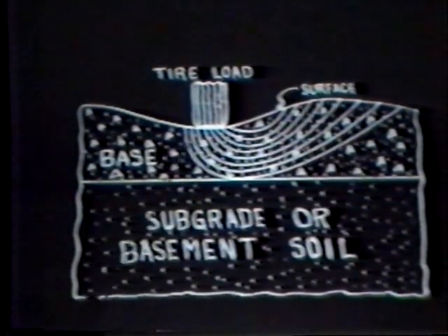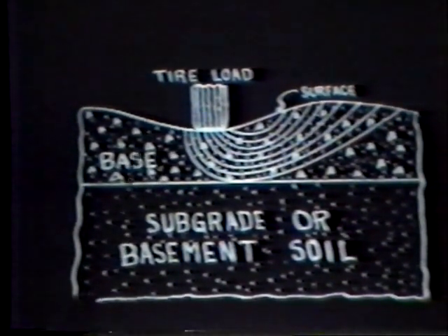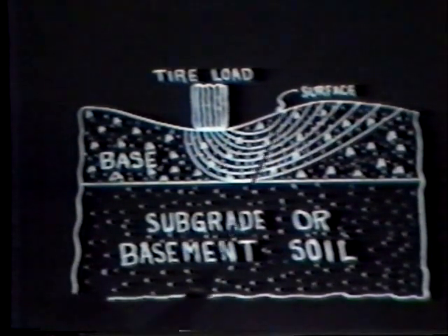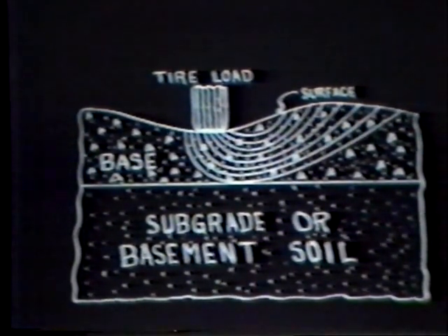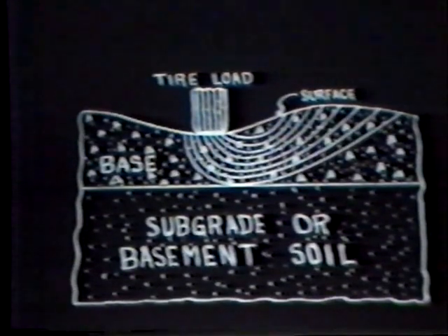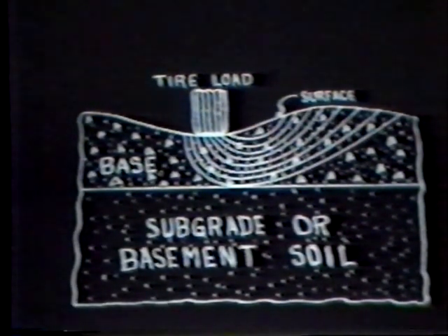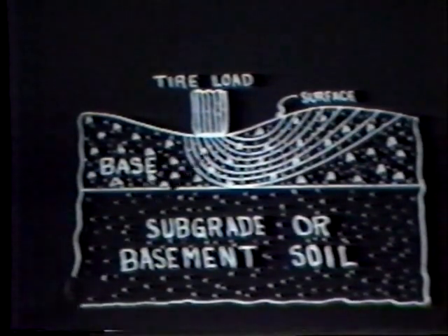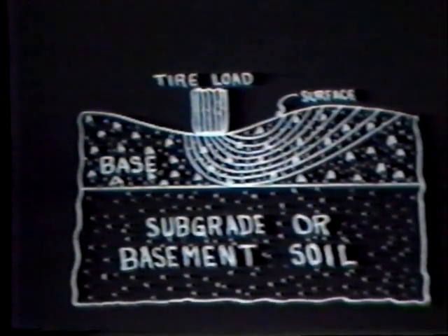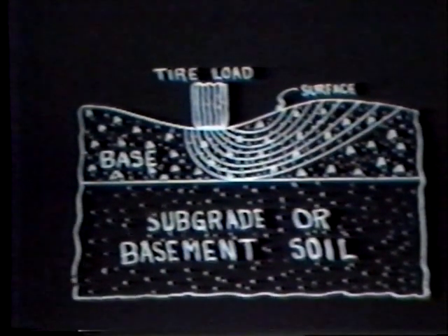And you don't want to use a weak base material or you will deform it, and you'll see a heaving in the surface. That's evidence that failure can occur either down in the subgrade or up in the base. But the principle is to transmit the tire load away from the stresses of the tire load, away from the subgrade.